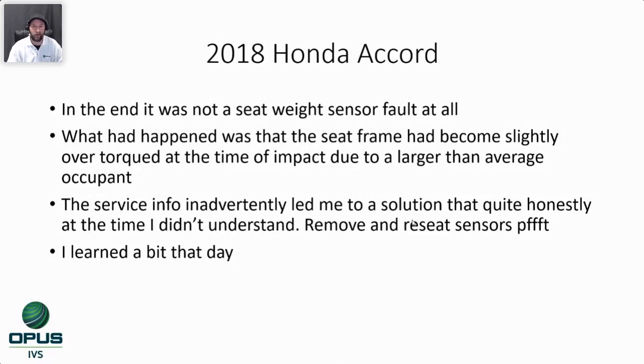So what happened was the seat frame itself had become slightly over torqued at the time of impact due to a larger than average occupant. The tip off for that was that the actual padding of the seat itself was completely worn down flat. Sometimes we have to be detectives in a way, and pay attention to some of the things that are there right in front of you.